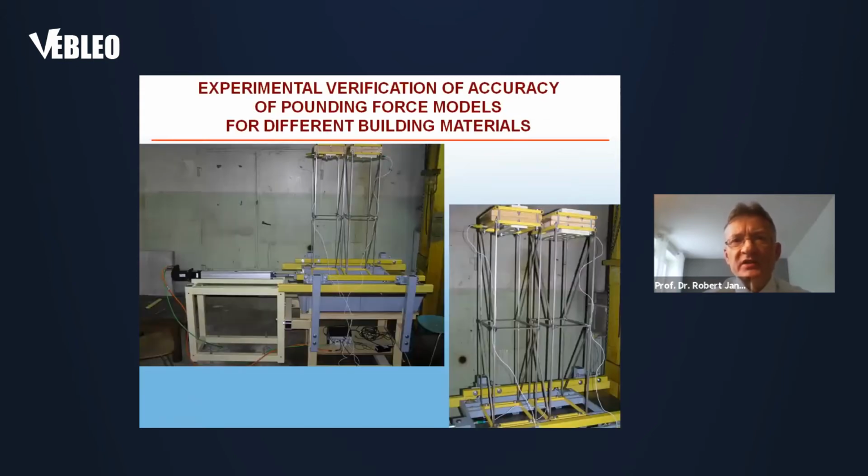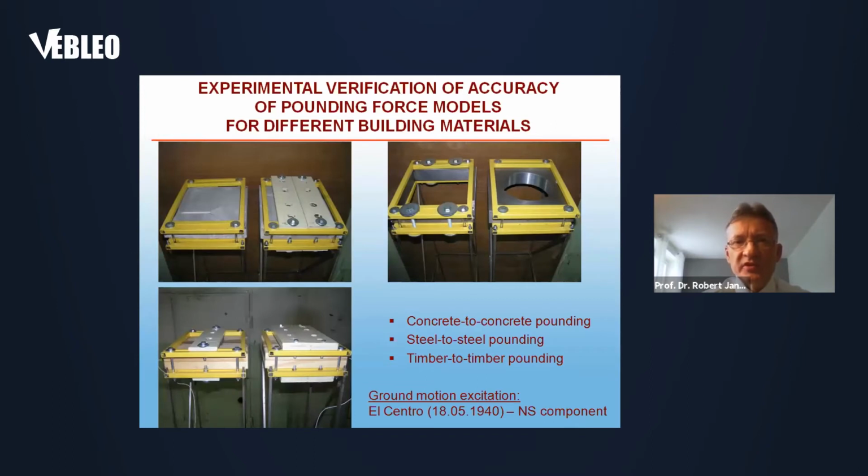Some experimental verification of the accuracy of different pounding force models was conducted using shaking table experiments, as can be observed in those two photographs. The experiment was conducted for different building materials, so we can study concrete to concrete pounding, steel to steel pounding, and timber to timber pounding, as typical materials used in construction.